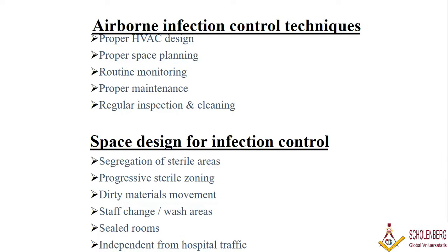I have seen many times the architects don't give proper space, and then the equipment is designed and installed later. It's very difficult even to go and maintain the equipment. So we need to understand this when we are designing an air conditioning system.